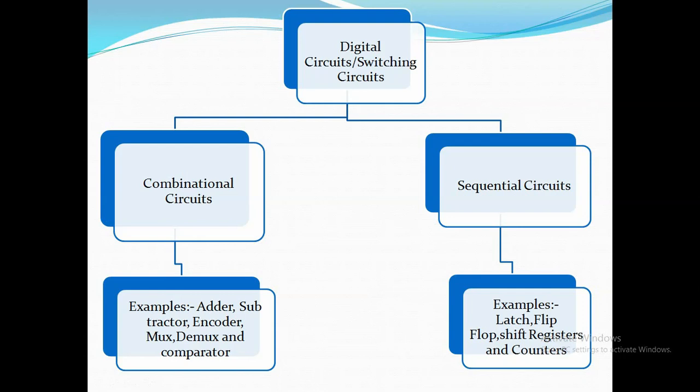In sequential circuits, there is another type of example, that is the shift register. In digital circuits, a shift register is a cascade of flip-flops sharing the same clock, in which the output of each flip-flop is connected to the data input of the next flip-flop in the chain, resulting in a circuit that shifts by one position the bit array stored in it.